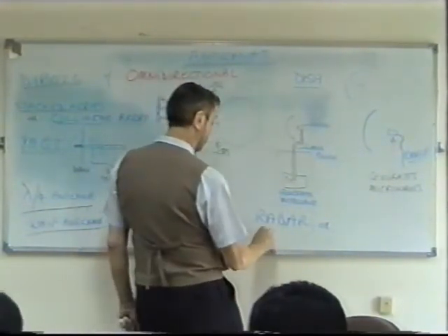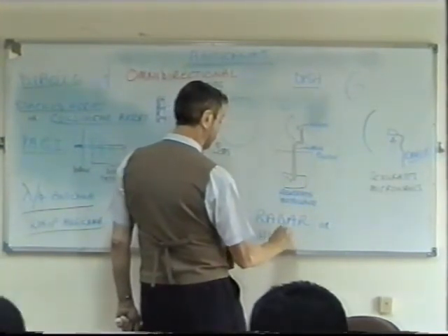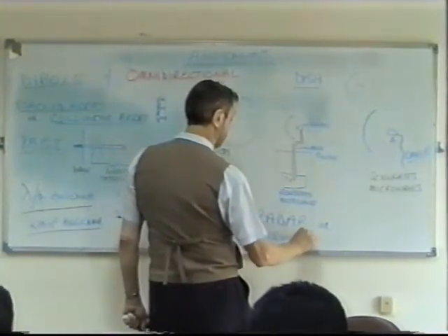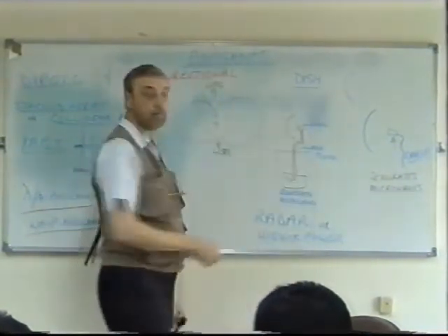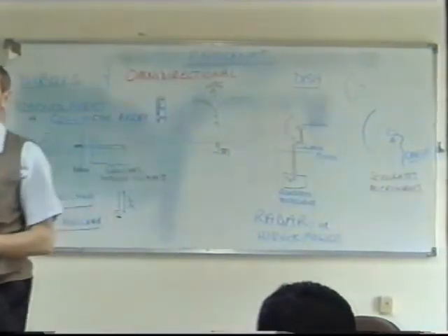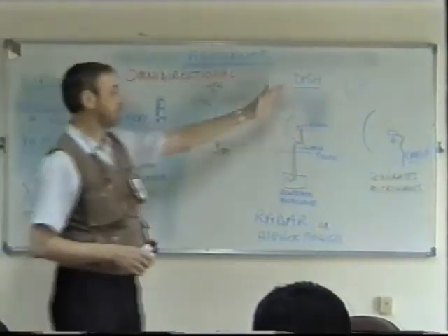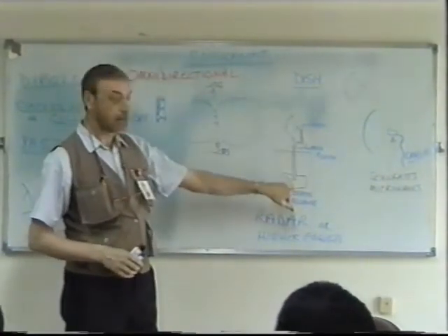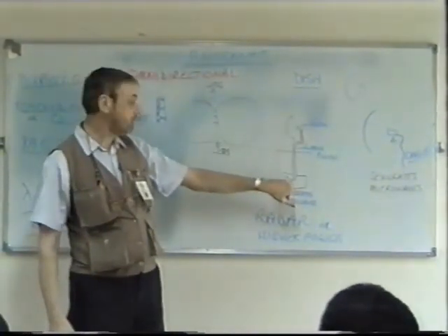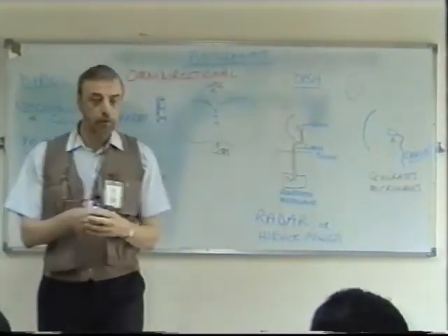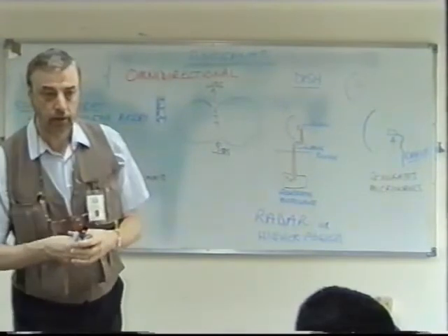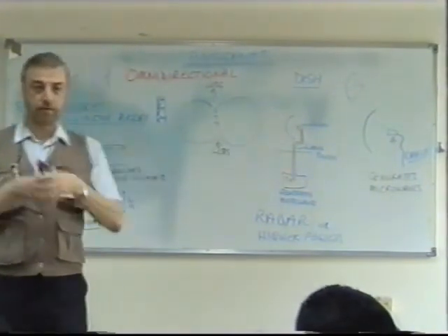Higher power anyway. Now, we don't use this in Saudi, so there's no use me spending too much time on how waveguides work, but I'm just mentioning this because it is another way in which you can get energy to the reflector. Sometimes the actual microwaves are generated remotely and then they have to be guided with this waveguide, which is only a pipe, copper or some sort of metal pipe.